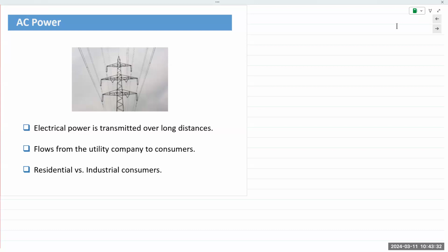The equation for resistance is rho L over A. It is directly proportional to the length of the conductor. So when it's 100 feet or less than 100 feet, it does not matter. But when it's hundreds of miles long, it does matter. Long distance electrical wires run for hundreds of miles. And when the L is hundreds of miles, resistance increases. And that resistance does rise to the level of interference.